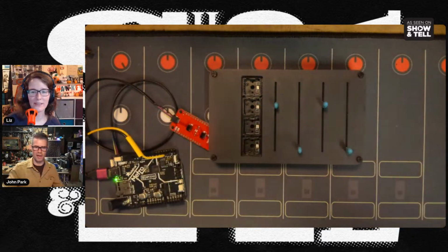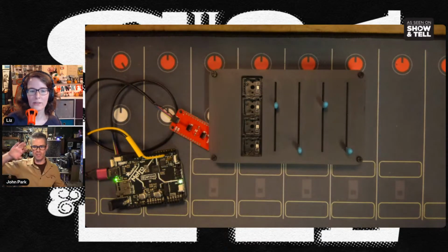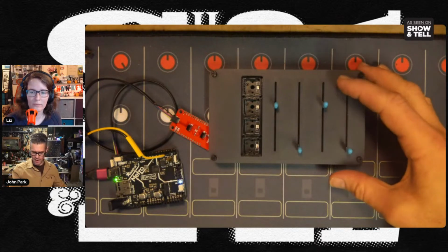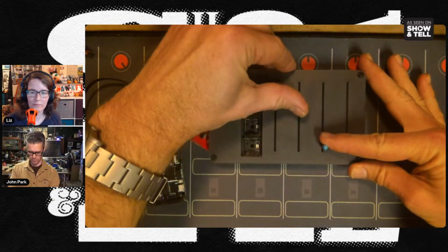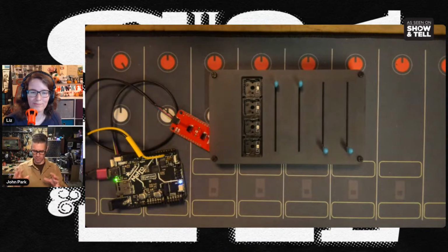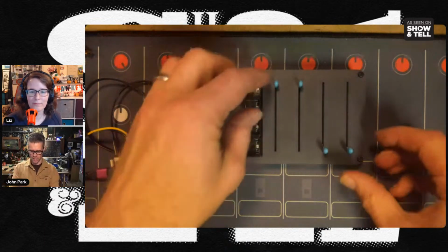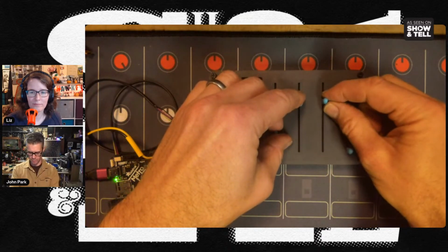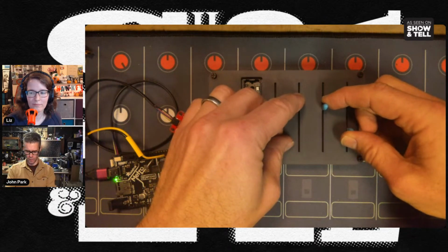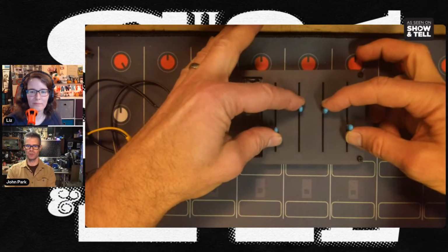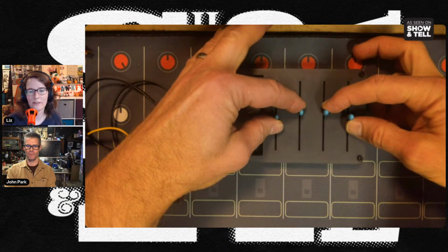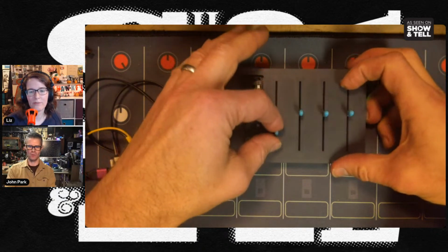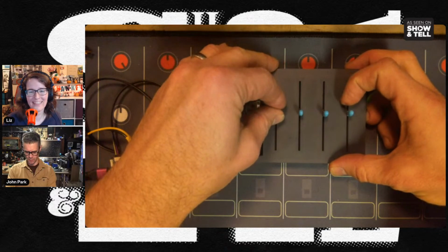So you can see here, this one is like a very sharp little sawtooth or a triangle. And so it's got these high-pitched, buzzy sounds that are part of its character. If I just do a straight square wave, it kind of loses some of that extra harmonics. And if I try to calm it into sort of a triangle shape, you can also quiet it just by shrinking its amplitude down. So now the waveform is sort of centered around 0. These go negative 30,000 to positive 30,000 each.